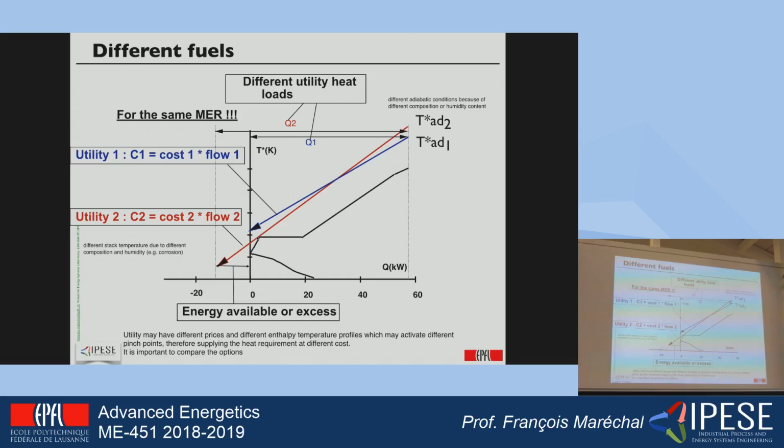So the Exergy explaining this, we know that if the temperature is lower, the Exergy value is lower. So what does it mean? Exergy is useful energy. Useful energy that can be turned into... Yeah, under which form? In form of work. So what does it mean? It means that if I'm supplying heat at 100 degrees C, and if I have something which is at 200 degrees C, between 200 and 100, I will have the possibility of producing work.